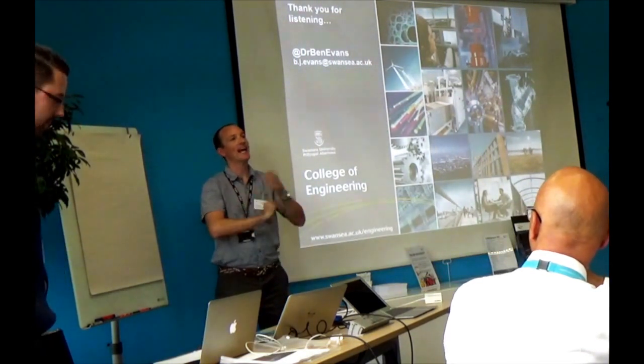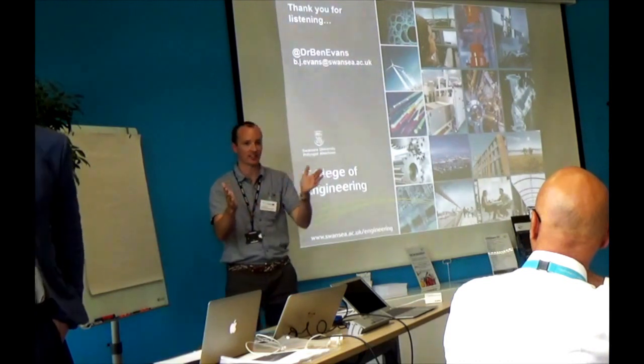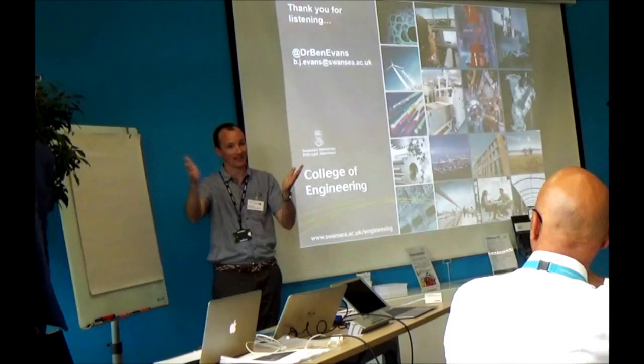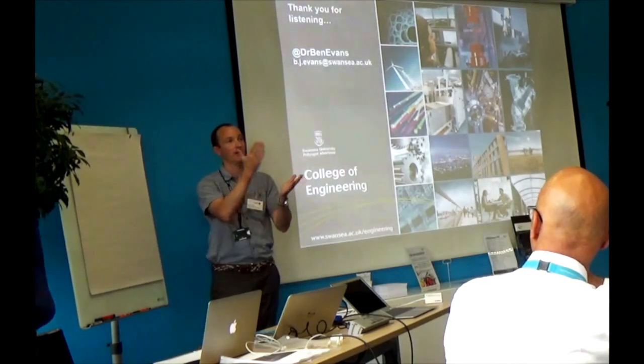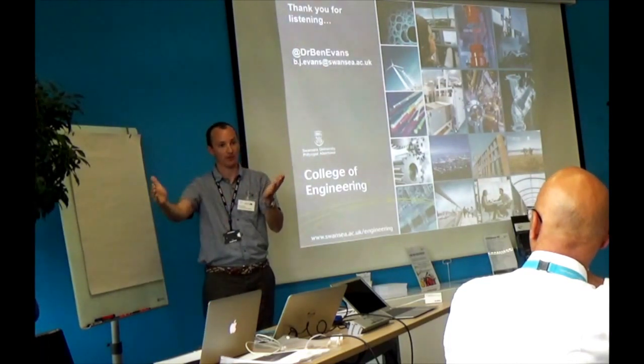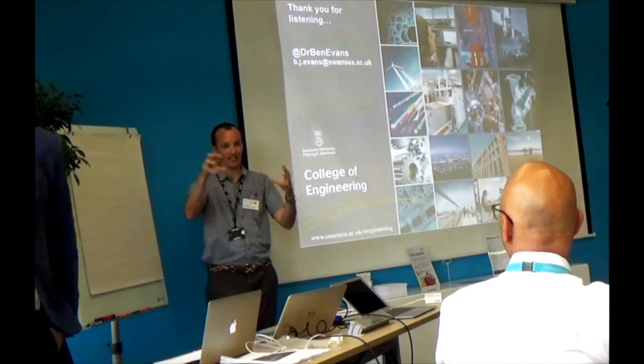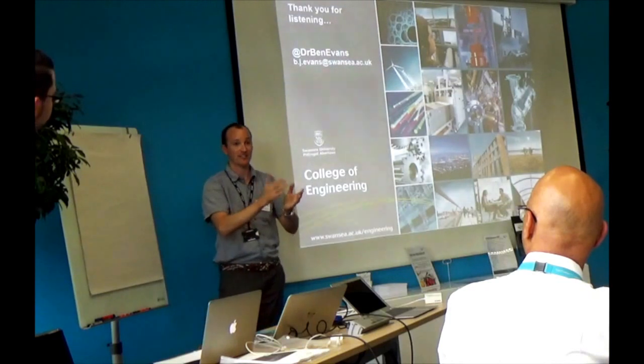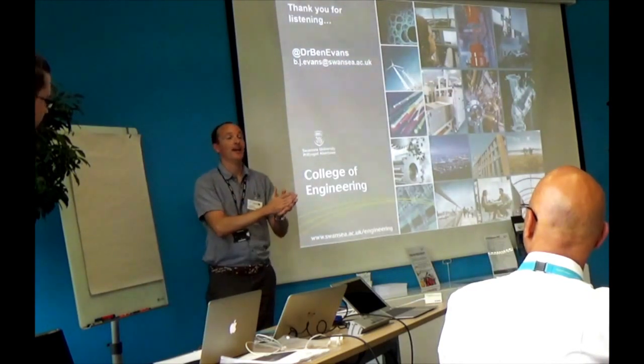Yeah. So when we're testing the car, we run these studies. We tend to pick four Mach numbers that we think are interesting: 0.5, 0.8, 1.1, 1.4. And we'll do that sensitivity analysis at those different Mach numbers. And yeah, you're absolutely right, you will find that the sensitivities are different in those different phases.